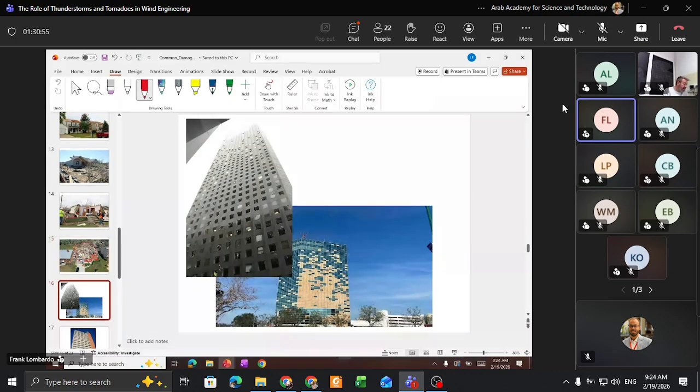Okay, here's what you might typically see for high-rise buildings. These pictures are both in hurricanes, one in Texas and one in Louisiana, so on the Gulf of Mexico coast in the US. What you see is a ton of window damage, cladding damage from debris, and sometimes both from wind pressure itself and from flying debris. A lot of windows then get knocked out.